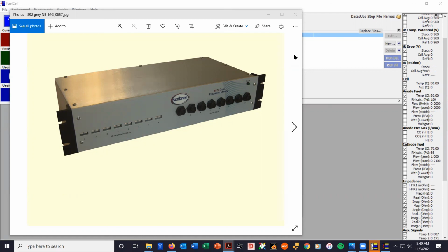But because we can't share, we're unable physically to share a single FRA between the load in the 850 or 890 and the 885 potentiostat hardware. We can't share hardware. So if you want to do impedance with both instruments, each instrument needs its own FRA.